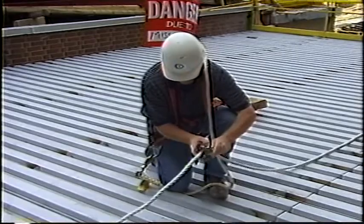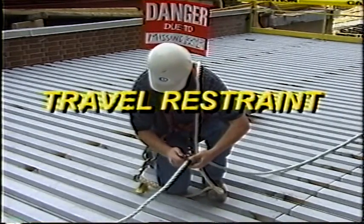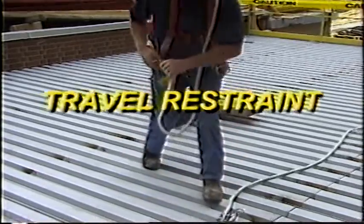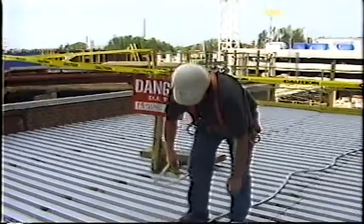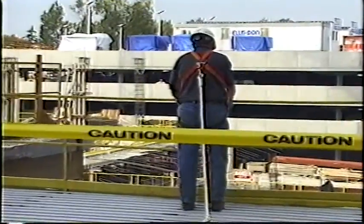When you must work near open edges, a travel restraint system can prevent you from falling. To work properly, the system must be arranged to keep you back from the fall hazard area. This may require continual adjustment of the rope grab to allow free movement and travel.